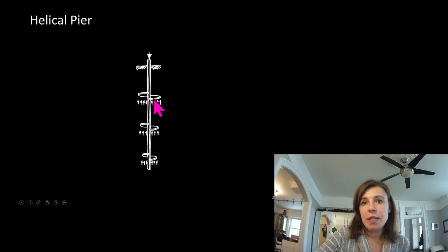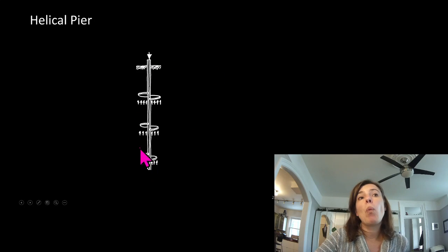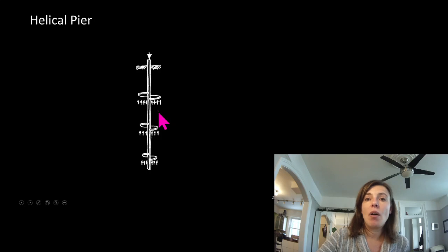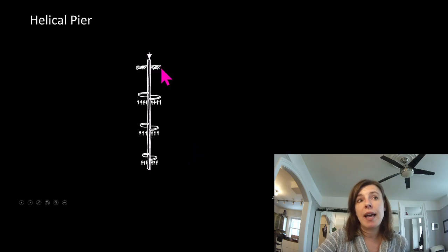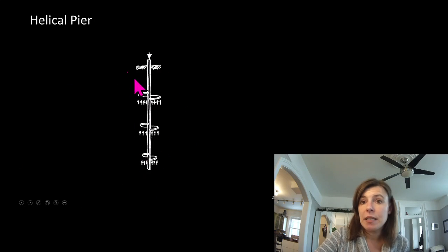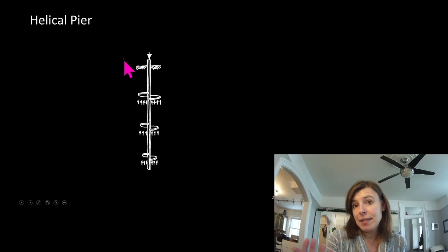What often happens in these projects is the base building engineer is given a preliminary feedback. The helical pier suppliers will look at the geotechnical report and give feedback on capacities. The risk is that when they actually screw the piers in, they might have a different capacity than what we estimated. It is a risk to the owner. It is often that they come out better than we expected, but sometimes it's worse. And in that case, the owner needs to be able to pay to get the capacity that we need.